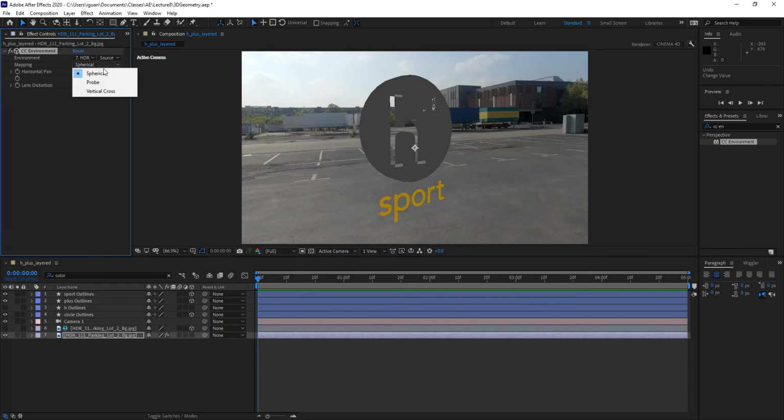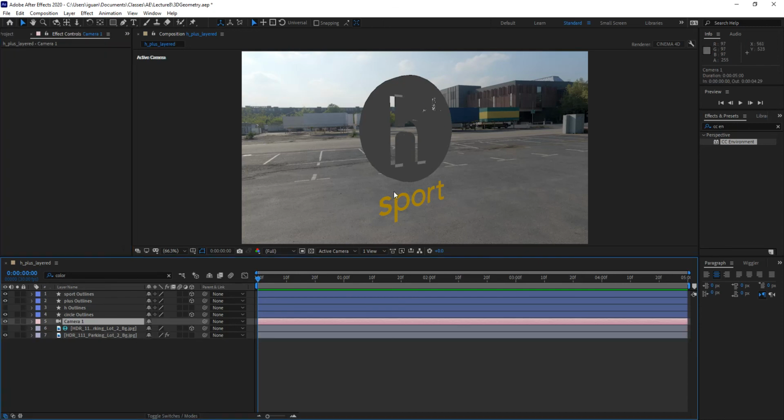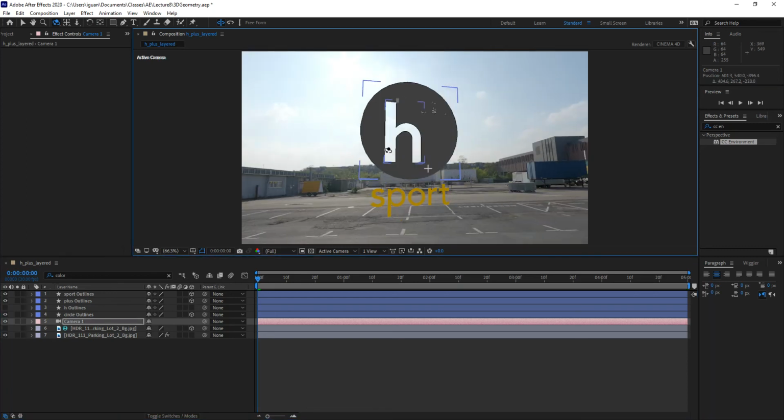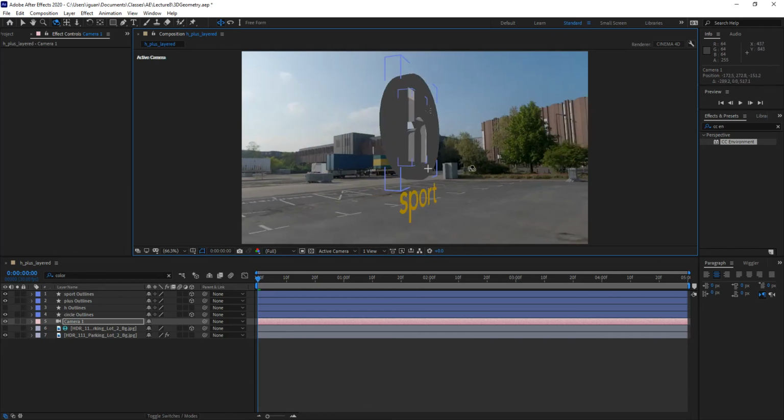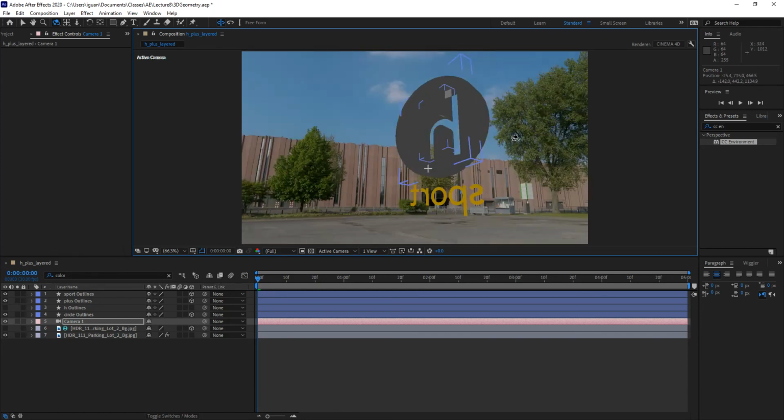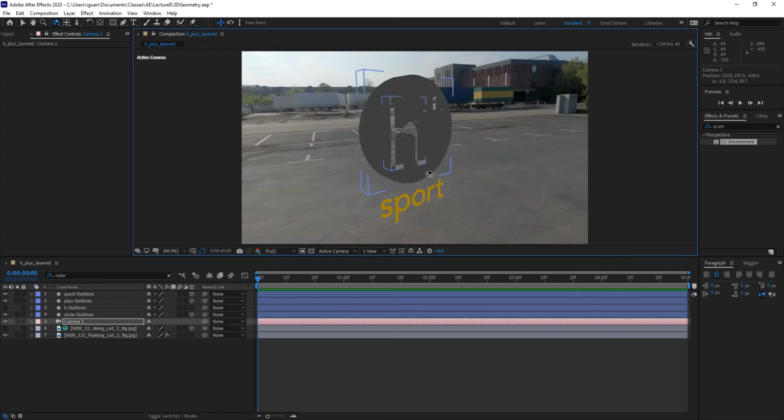You can also choose how that image is mapped onto that filter. In our case, it's spherical because of the type of image that we're using. Remember, our HDRI image is a 360 shot. What is cool about this filter, though, is that it obeys the position of my camera on the screen. So I can go ahead and switch my tool to the orbit tool, and you'll notice that my camera rotates, and I am seeing the entirety of the parking lot as if I was actually in it. So basically what it did is it created a sphere around my environment and mapped that HDRI image onto that sphere, creating therefore ambience for the scene.